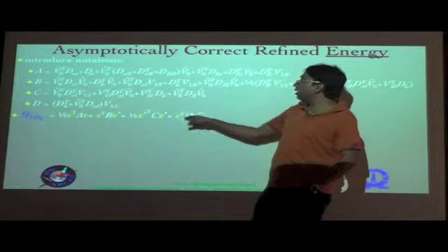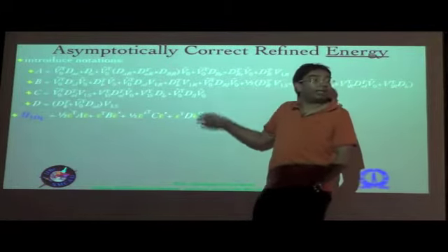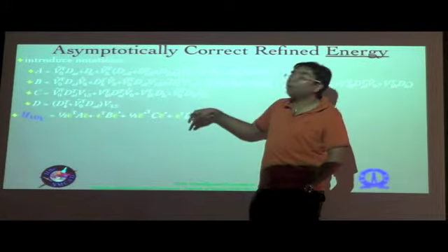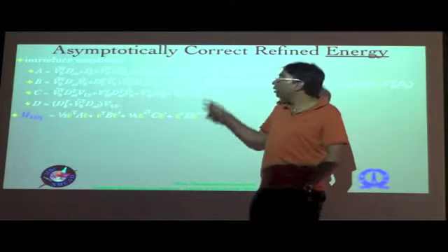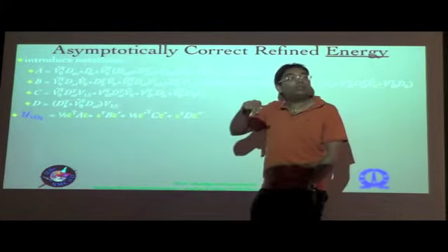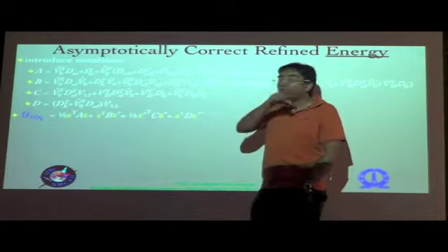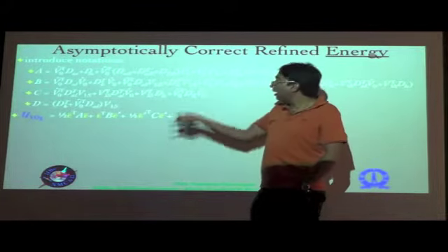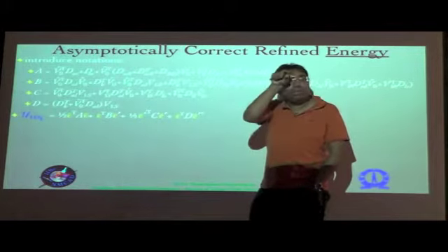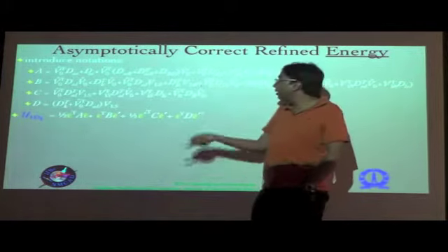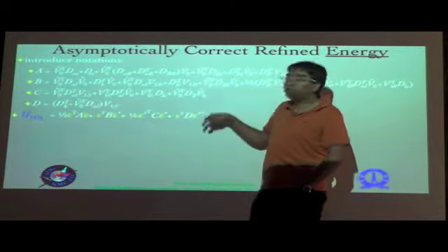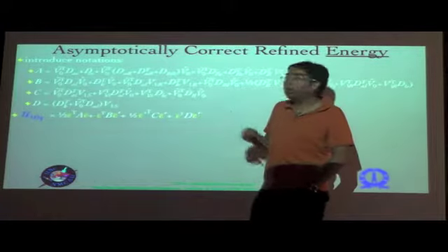But you also get a term which has the second derivative of epsilon bar coming into the picture in the U1 D1, because remember that your energy has derivatives with respect to the x1 direction as well, and one of the terms which comes from that, because you have the warping solution depending on epsilon bar, therefore you will have epsilon bar prime, therefore its derivative with respect to x1 will have a double prime as well.